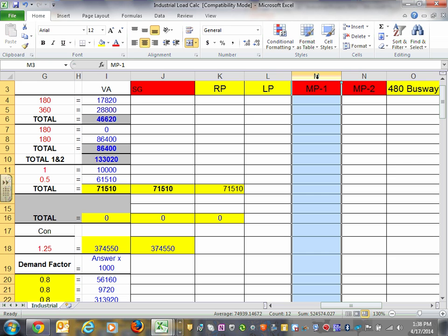Voltage drop issues, so 225, maybe 300. That's a good number, at least in my mind, when I do receptacle and lighting panels. I want to stay within 225 amp panels, 300 amp panels, but definitely not 600 amp. Anybody have a 600 amp receptacle panel? Maybe for, and we're not talking about PDUs here for data. That's a whole different story for racks and what's not.